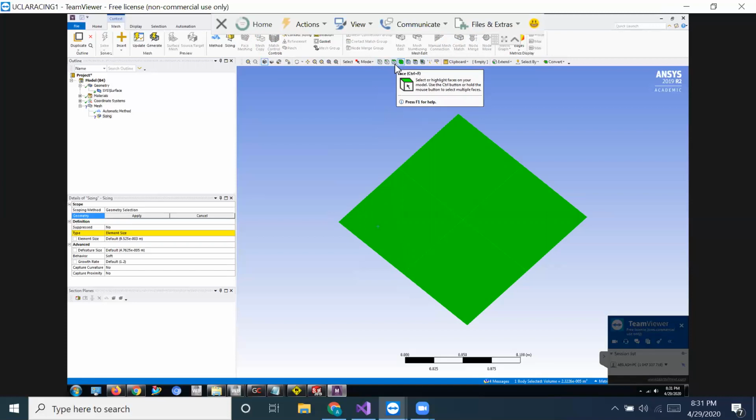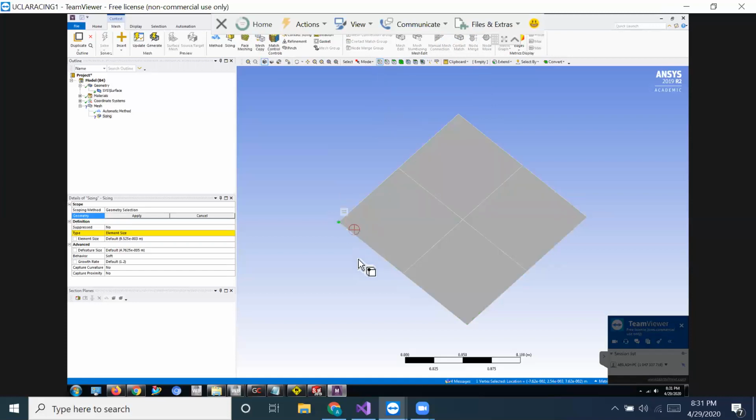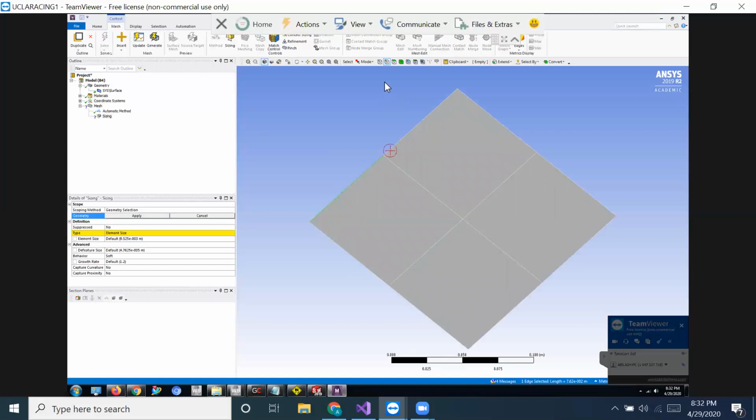There are different selection methods. In this case, you have 4 different selection methods. One is vertex. Vertex allows you to select a point. In this case, I'm just selecting this point. That's not what I want. Second is edge, which will allow me to select an edge, a line up to the nearest breakpoint. In this case, there's an intersection here, and this is the breakpoint, so I'll select only up to this edge. You can see the selection is whatever is highlighted green. Next is face, which will just select the broken up face, so the split face.